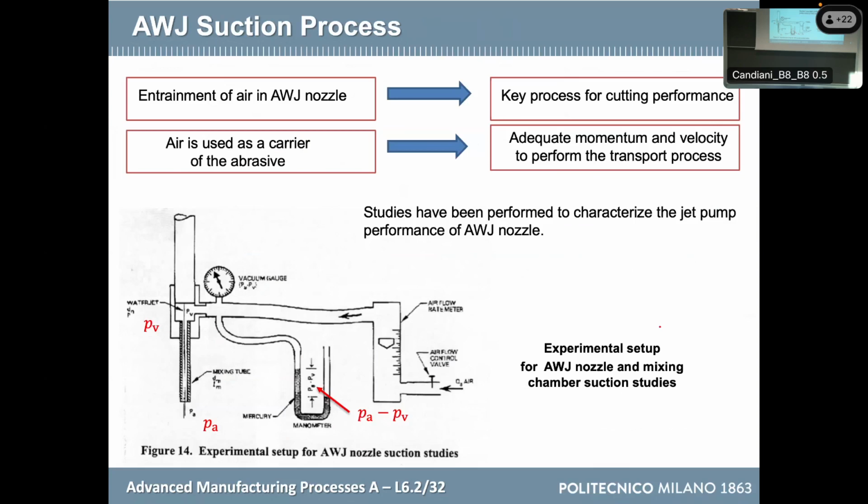And in this way, you can protect the jet so that it stays stable. But in the case of abrasive water jet, the jet is as large as the bore of the focuser. So there is no space for the air to come up. Okay, so what you say is physically right, but air cannot come here. So?